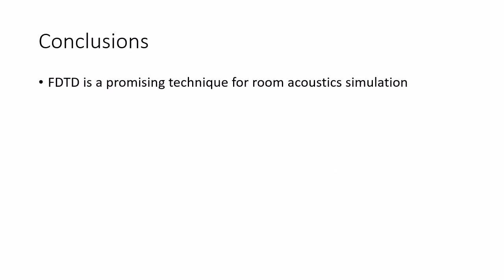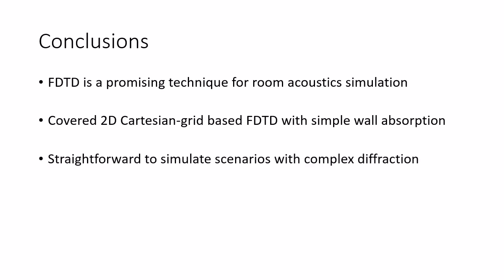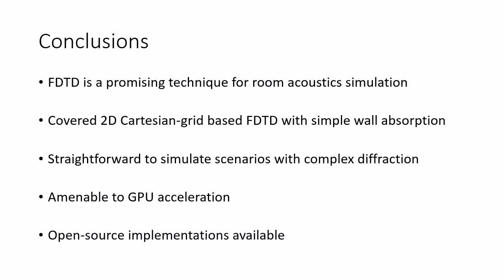So to conclude, FDTD is a promising technique for room acoustic simulation. I've covered a basic 2D model, Cartesian grid-based FDTD with simple wall absorption, and I showed that it's straightforward to simulate scenes with complex diffraction, and it's well suited for GPU acceleration, and there are open source implementations available that you can use.